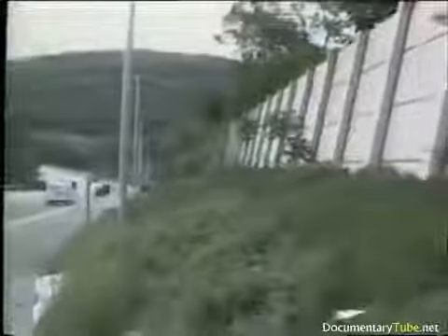Solutions to parallel barrier degradation include: 1. Applying absorbing material to the face of the barrier, and 2. Tilting the barrier out away from the highway. When tilting a barrier, one must consider tall structures on the opposite side of the highway so as not to adversely affect them with the reflected sound.